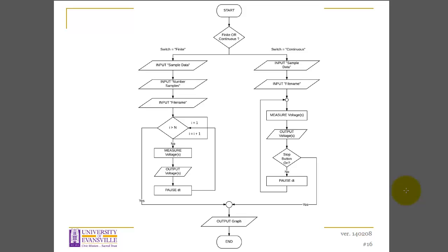You're going to build your own Wheatstone bridge, and instead of using the strain indicator to condition and amplify that signal, you're going to use LabVIEW to measure that analog voltage output from the Wheatstone bridge, convert that to a digital signal, and then measure that and treat that so that you can actually calculate the strain. And hopefully that'll provide a wonderful opportunity to synthesize the separate topics you've been learning these past 5 weeks in the course.